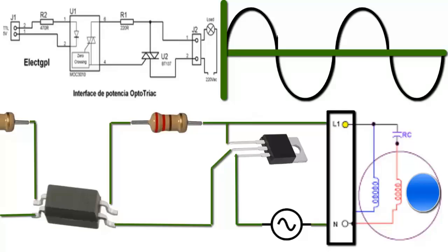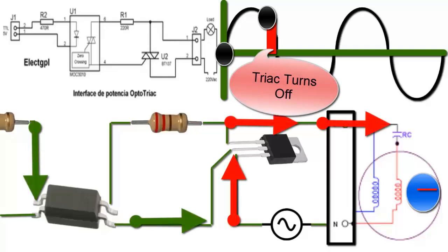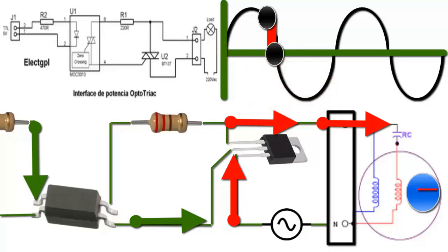On the other hand, when a low speed is desired for the motor, the controller waits for the zero crossing of the voltage curve, delays more time without activating the signal to the optocoupler, and in this way, maintains the activation of the voltage from this optocoupler for less time. In this way, the motor receives less energy, resulting in slower rotation.